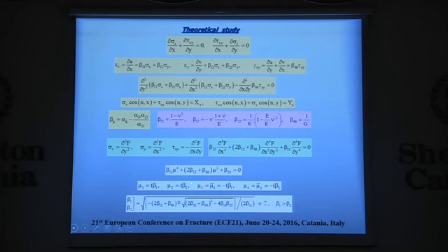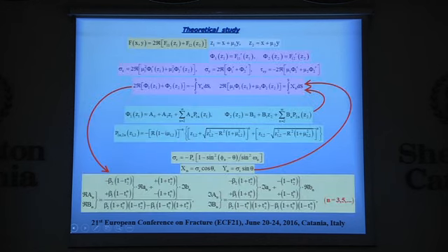By means of these complex parameters, we can define these complex arguments, the so-called generalized complex arguments, and in turn these two functions, phi1 and phi2, which are the complex potentials of Lekhnitskii, in terms of which we can define the real stress function F.